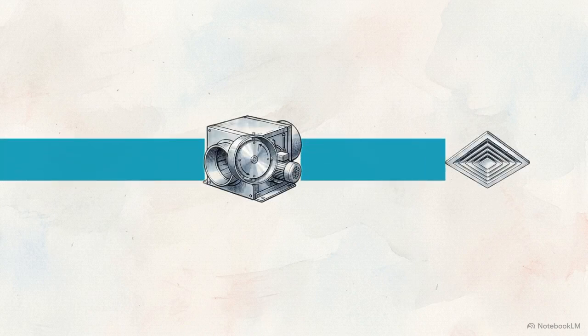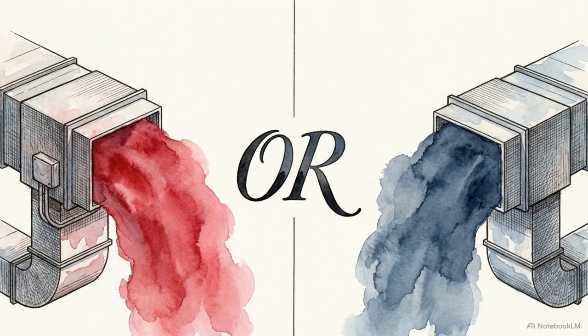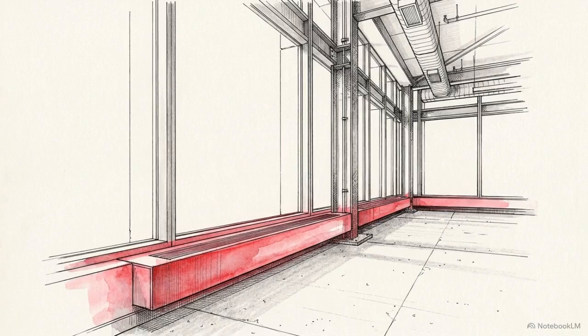As a room's thermal load decreases, a terminal VAV box mechanically throttles the airflow, reducing the volume of cold air entering the space. A pure VAV system has a strict limitation. It can either heat a zone or cool a zone at any given time, but it cannot do both simultaneously without being paired with auxiliary perimeter heating systems.